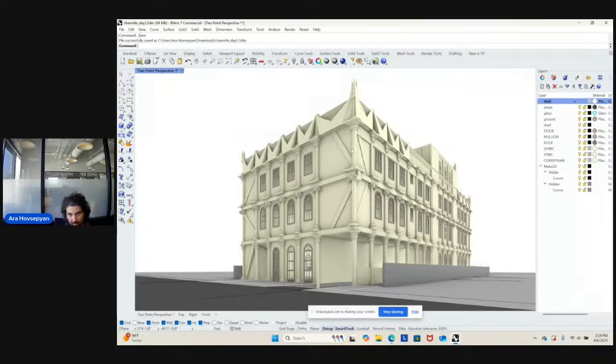And then you go back and extract what are essentially like the CAD scans of it. You cut floor plans through each floor, you cut sections through the longitudinal direction, and then you cut the cross section, and then you make the elevations, and then you draw on them more accurately. So using Rhino is quite an iterative process.